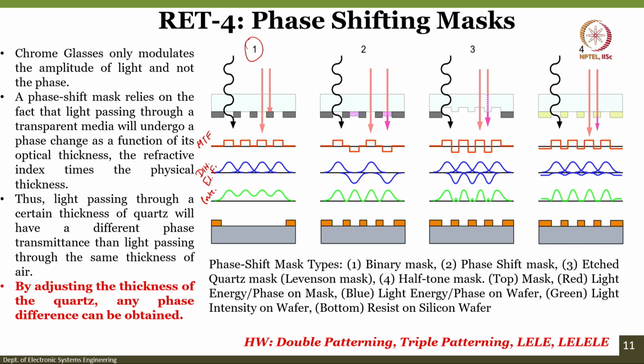So, you see here this is the simple mask what we have been seeing, this is 1, this is 0, 0 1 0 1 0, simple. You are getting this kind of diffracted pattern where, as I mentioned, side lobes get eaten by each other and you will get this kind of intensity. And with this intensity when you reach the wafer your PR will get affected like this and you will get this profile. See what you want in the mask compared to what you get here. Let us see the second example now.